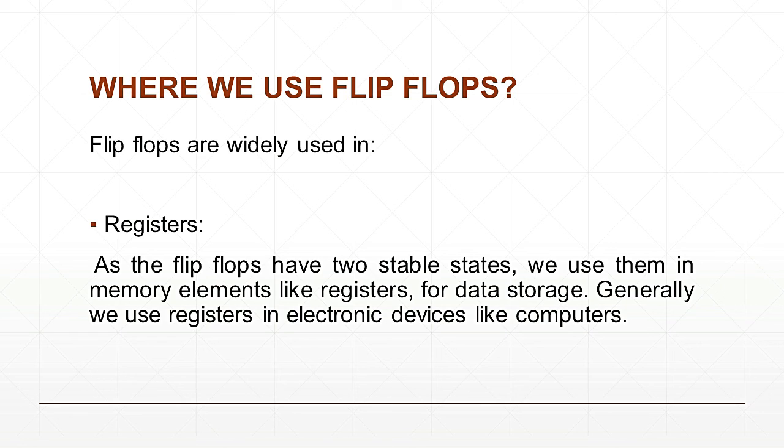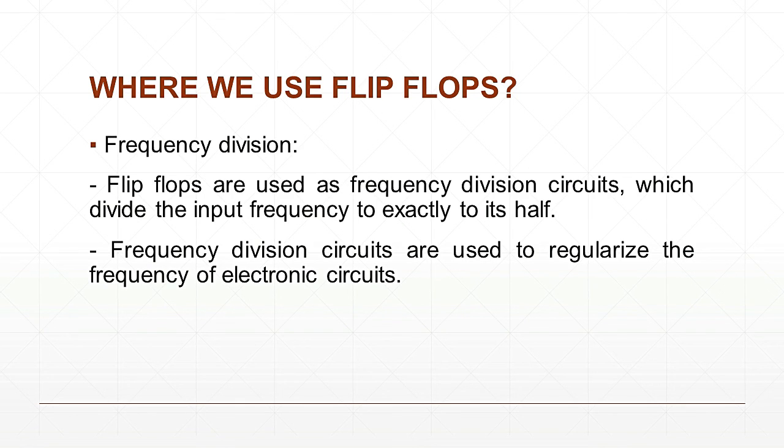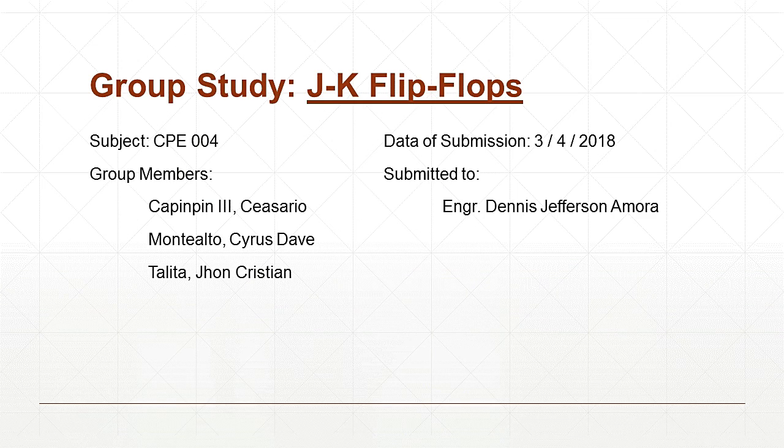Where do we use flip-flops? Flip-flops are widely used as registers in electronic devices like computers, as counters to count increment and decrement, as data transfer, and as shift registers from one flip-flop to another, and as frequency division, which divides the input frequency to its half.